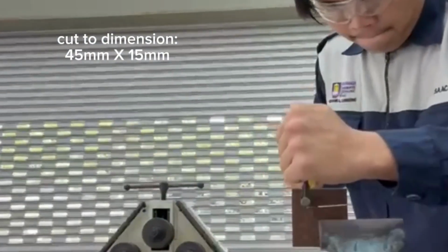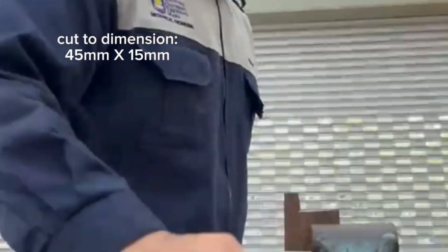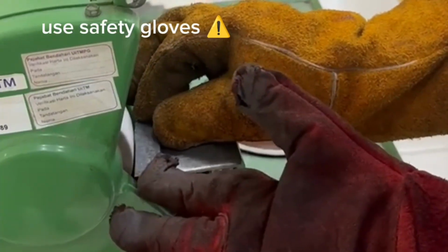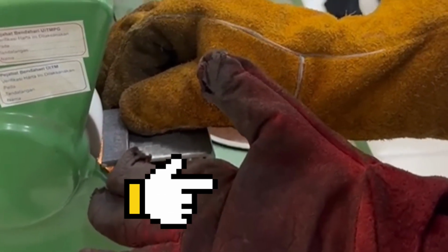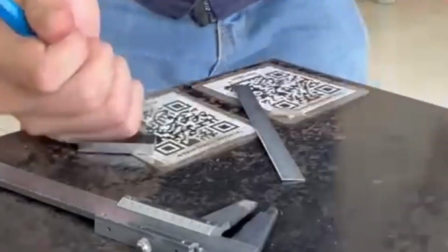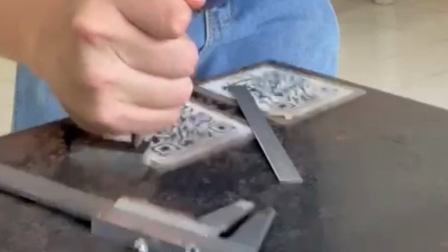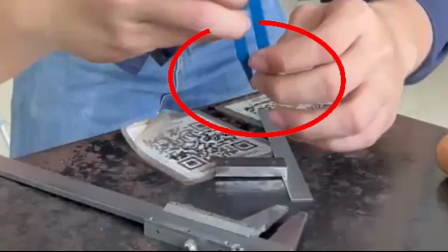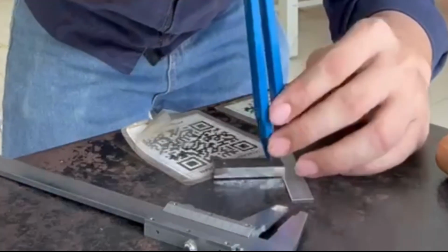First, we cut the provided metal sheet into a piece measuring 45 mm by 15 mm. After that, we remove any rough edges by grinding, and during this process we need to use gloves to ensure safety. Next, we tap the 3 holes according to the drawing. After that, we use a radius gauge to mark the half circle profile between the first and third tap holes before machining.